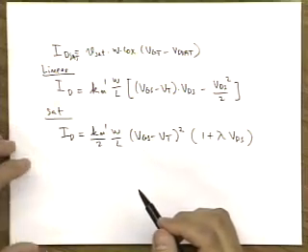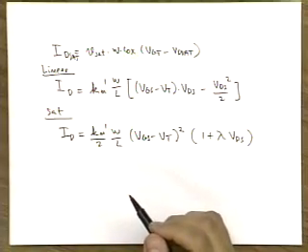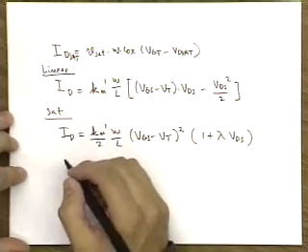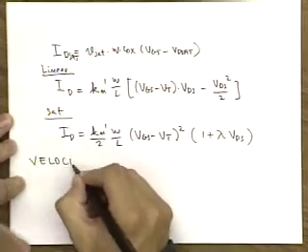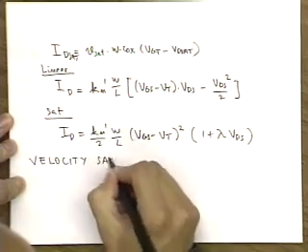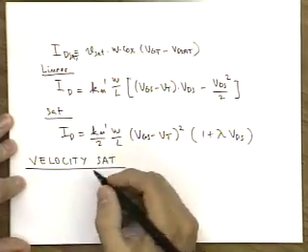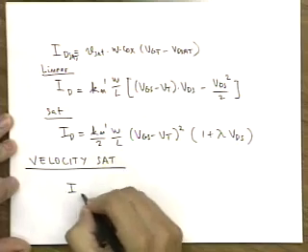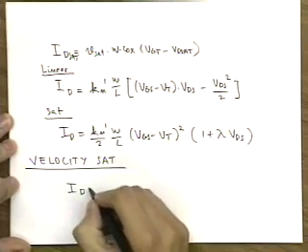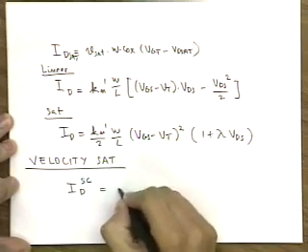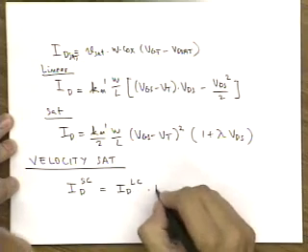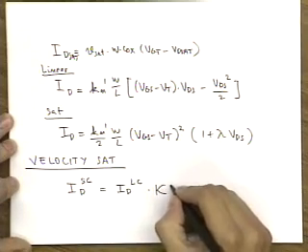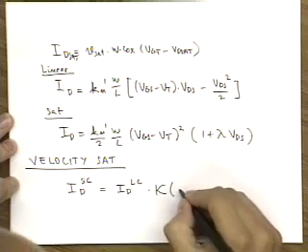Now when we go over to the short channel model, then we have this effect of velocity saturation. And basically what this changes is that your ID short channel is equal to the ID of a long channel times this parameter K of VD sat.